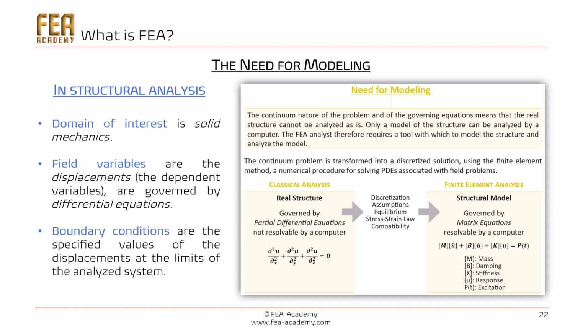So the continuum nature of the problem and of the governing equations means that the real structure cannot be analyzed as is. Only a model of the structure can be analyzed by a computer. The FEA analyst requires a tool with which to model the structure and analyze the model. So, during this process, the continuum problem is transformed into a discretized solution using the finite element method, a numerical process for solving the partial differential equations associated with the field problems.